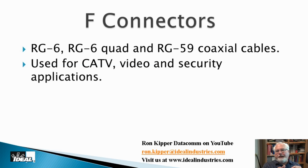I'll give you a great example: component video cable. That's that red, green, blue wire you hook between a set-top box and a TV. If you ever cut that little cable in half, it's 1/8 inch in diameter, it's actually mini RG59, it's coax. So say you needed a 50-foot-long component video cable, could you not make it out of RG6 and put RCA connectors on the end of that cable to make a longer component video cable? You sure could, because it's all coax, it's all 75 ohms, so it's all interchangeable. You could if you care to.